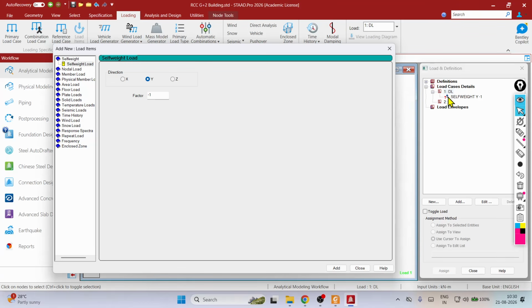So what we will do, we have to again see what type of dead load is there. The other type of dead load is the brick wall load that is going to be on the beam, correct? As per 875, if I am using red clay brick, the unit weight of red clay brick lies between 18 to 20 kilonewton per meter cube. And I'm assuming our wall thickness is 9 inches, it means 230 mm. 9 inch means 230 mm.